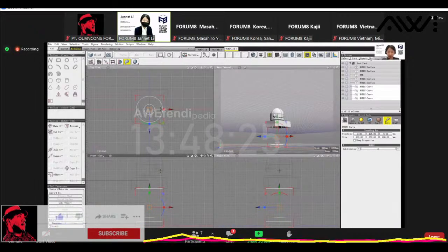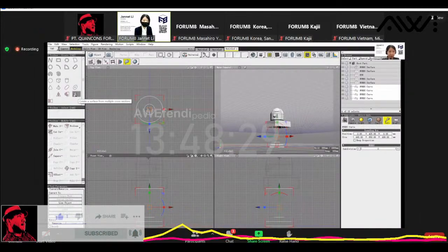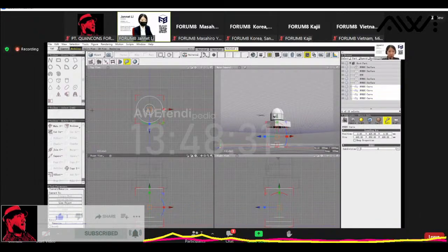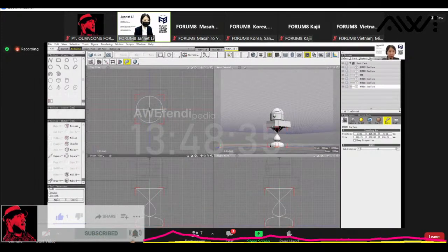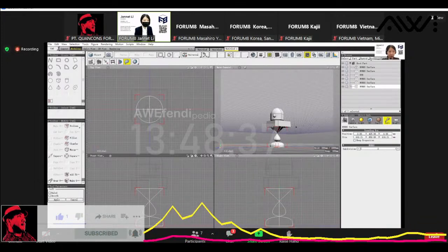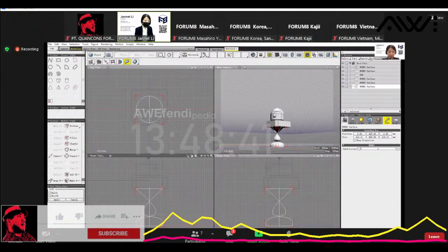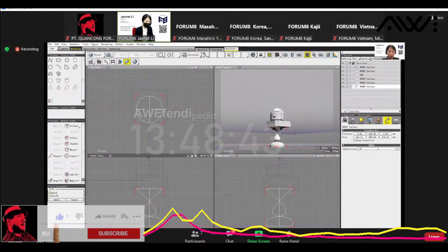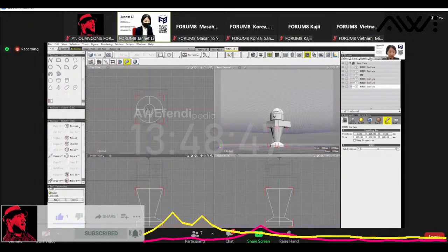Now, let's press Control and pick all 4 of the NURBS curves, and you can see all 4 of them have been created when you look through the meta camera perspective. Let's go into Create, go into Loft, press it, and there's a shape that has been generated, but this is not the one that we are looking for.